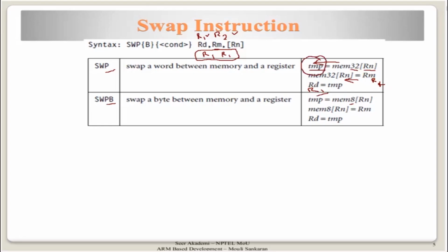What is this temporary location? Is it a memory or a register? It is a register inside the processor. We don't know how; it could be a buffer maintained by the processor. It copies the value which has been read from the memory and temporarily keeps it here. Then, since I am interested in changing the R1 value, it goes back to the same location in the memory.